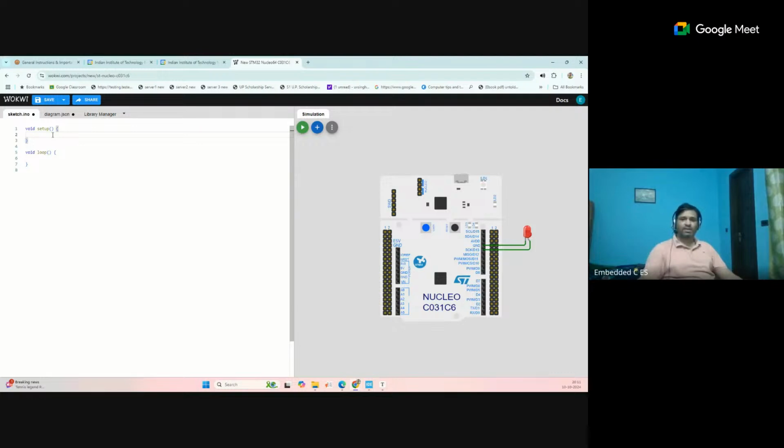So the first thing is the setup. Here there are some predefined functions, so we can write pinMode. It comes automatically when you type. So pinMode, and which pin we are using for the output, that is pin 13. Here we have to pass two parameters: the pin number, and which mode we want to use this pin in, input mode, output mode, or input pull-up. We simply want to use it as an output, because we are just passing output to the LED. So we select that here. Now this pin is configured as an output pin.